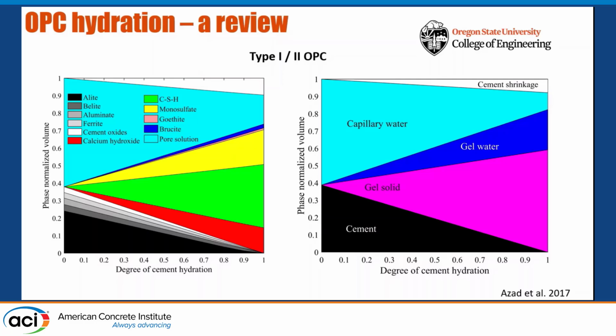That means that you're basically waiting, the concrete or paste is aging, and as they're consumed, you start forming all the good stuff that we like in concrete. You produce CSH, which is the glue that holds things together. You produce calcium hydroxide that partially gives that high pH, high alkalinity to your concrete, which has other benefits for concrete. You produce monosulfate, which again helps your porosity, etc. Some part of it remains as water, and you get some chemical shrinkage.